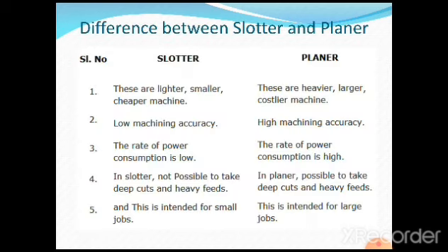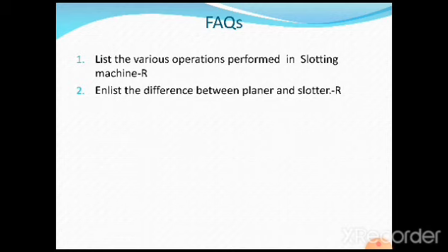This is also an important question. I have discussed at length the differences between the two, that is slotter and planer. But we need to understand whether the difference is discussed in connection with the shaper and the planer or the slotter and planer. Compared to the shaper and slotter, the planer machine is a big one and used for heavy jobs only, whereas the shapers can be used for small jobs and very less complicated operations, but the planer is basically used for heavy jobs. So these are the expected questions to come in the examinations.